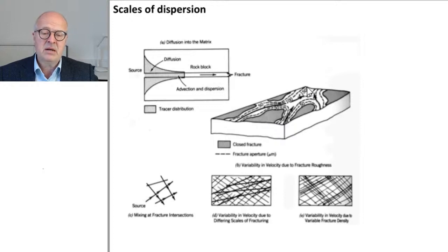Now, as you see, there is at this very small scale dispersion already in different pores. Then you have dispersion by different packages of sediments. And finally, you leave the river and you get dispersion again because river sediments alternate with completely different sediments. And if you scale this further, you can imagine that you get into another geology, and this was not a fluvial sediment anymore. Maybe it is Aeolian sediment or another type, and dispersion increases even furthermore.